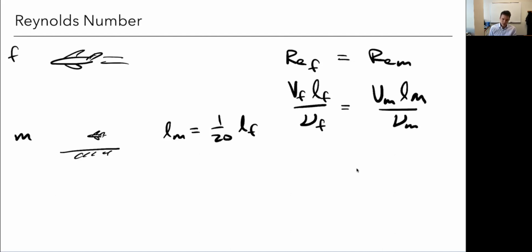And it turns out that the kinematic viscosity is actually quite a bit higher at altitude. The dynamic viscosity is higher on the ground because I have higher temperature, but the density drops so much more significantly as I go up, so that the kinematic viscosity is actually bigger up at higher altitude. So the full scale is, say, somewhere between 2 to 3.